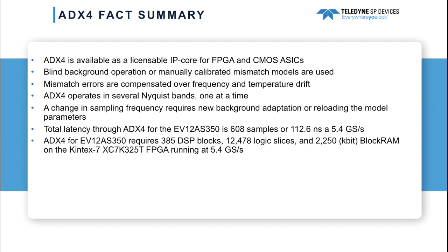Total latency through ADX4 for EV12AS350 is 608 samples or 112.6 nanoseconds at 5.4 gigasamples per second, which makes ADX4 suitable for non-latency critical applications. A complete EV12AS350-ADX4-EVM evaluation kit is available for $5,700.